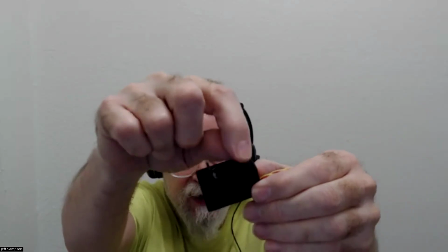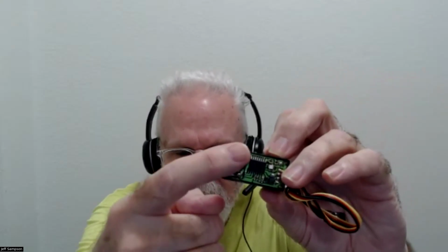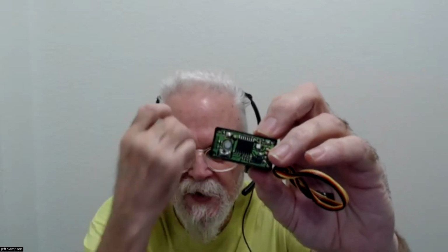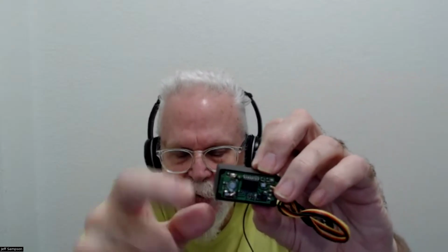But sticking up right here is the top of the pot right there. So the pot turns back and forth. That's your positioning. And what you have to do, everybody says, is unsolder the wires to the motor. So that's these two tabs sticking through there. You can unsolder that, and I think you can probably pull the motor and the board out. I just need to find a screwdriver and pry on that.